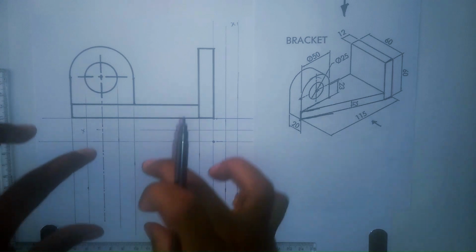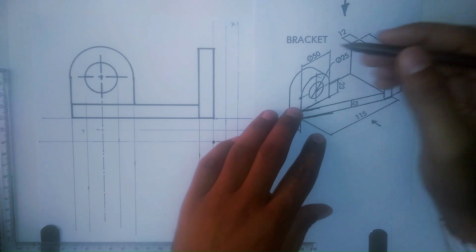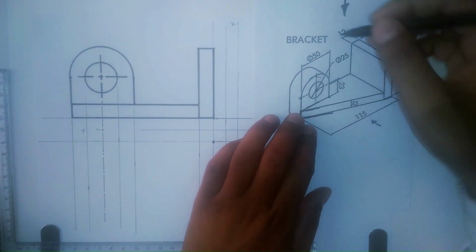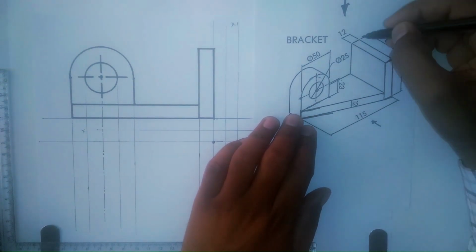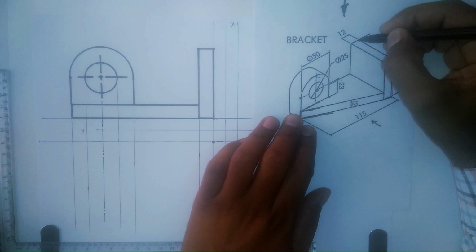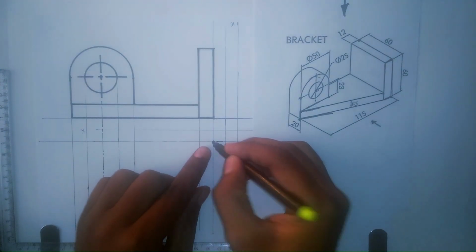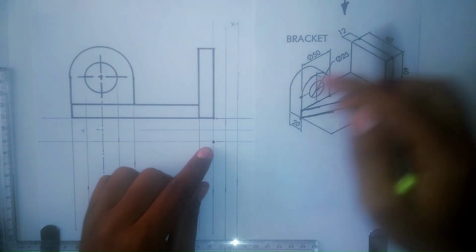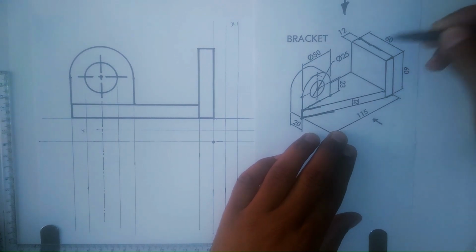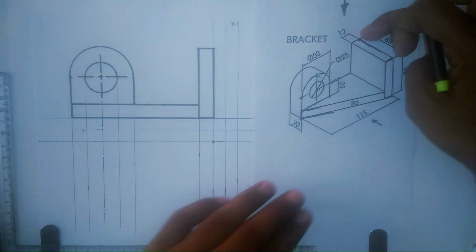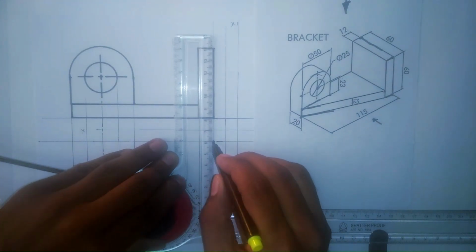Now here we have to draw the top view. So this is the right hand upper point of this top view. So when observer looking at this object from top, from this direction, this is right side and this is left side. This is bottom and this is top. So right hand upper point will be this point, means this will be starting point of the top view. In the top view, the starting point I have shown here and here in actual object. So I have to draw this line which is 60 mm long. So from this point in downward direction I have to draw 60 mm long line. So this is 60 mm long.